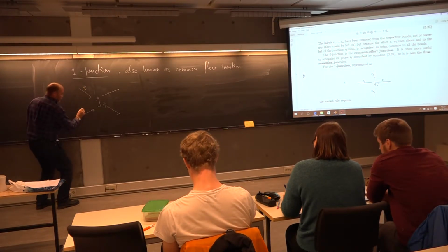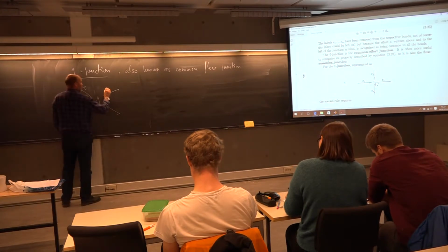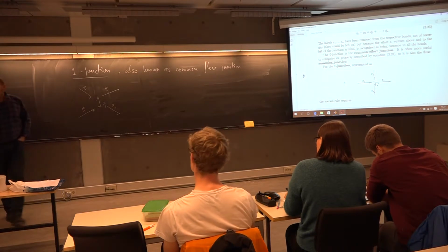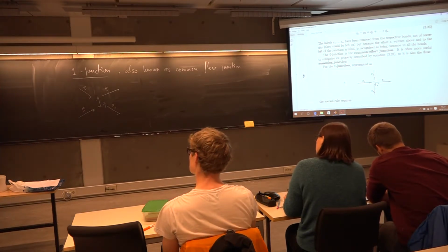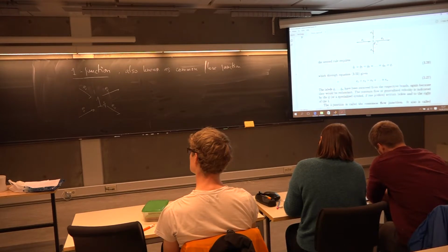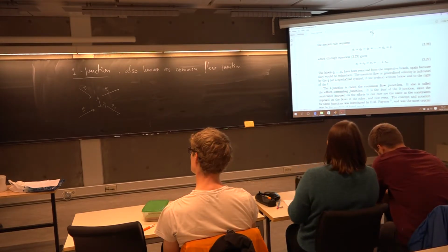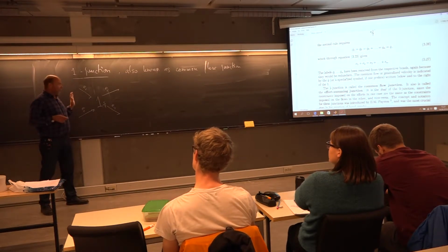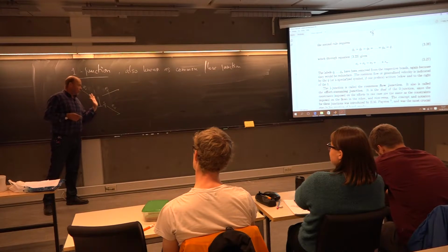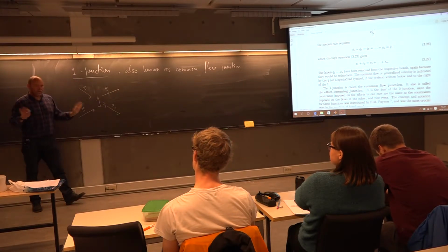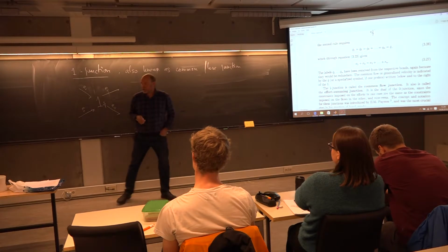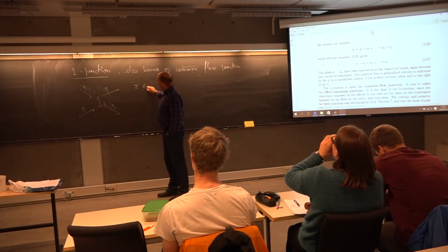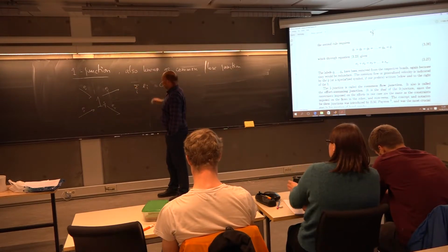So here we have effort 1, effort 2, effort 3, and effort 4. So we will have the same here as with the zero junction. When you now use the sum of all powers entering the one junction, it must equal all the power exiting. No loss of energy, no production of energy. So here the sum of the efforts equals 0.